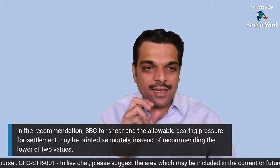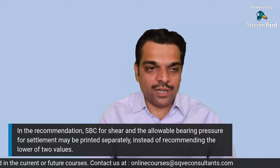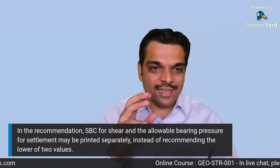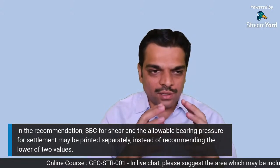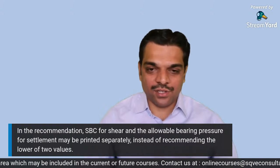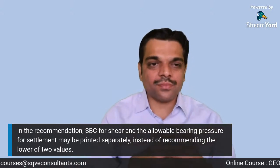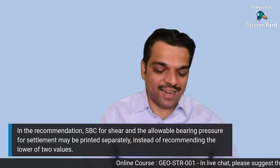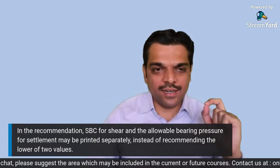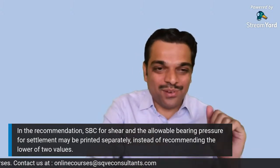Now this is a big area actually. See, what is said is that in the recommendation, the SBC for shear and the allowable bearing pressure for settlement may be printed separately instead of recommending the lower of the two values. In the course, I'll give a very detailed elaboration on this aspect, because I was always insisting on the SBC for shear and settlement separately from the geotechnical consultant, because there is another practice also going on wherein the lower value will be given in the geotechnical investigation report. What are the pros and cons of both, we will discuss in much detail during the course. But this is a very important question: should separate values be given in the report, or should it be the lower value?